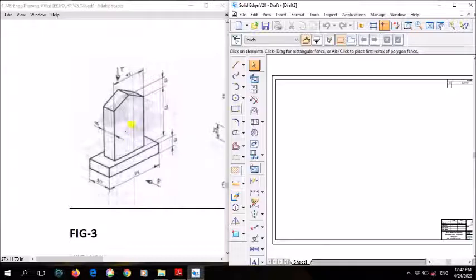So here we'll draw the front view, the top view, and the right view. The right view is drawn on the left plane. Let's start with the front view. Before going ahead, since we are drawing the right view, your front view will be here, your right view will be here on the left plane, and your top view will be here.